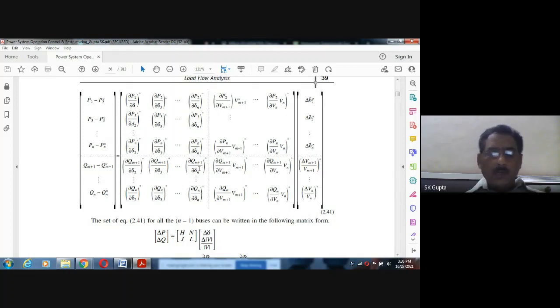And once you calculate this, take the inverse of this and multiply here, because with the help of MATLAB, it is not difficult to take the inverse of a 100 by 100 matrix. Then multiplying is also simple. Then this error or correction can be calculated. This correction will be added to the initial estimated value, then the first iterative value will be obtained. That first iterative value will be considered again, and the process will be repeated till two consecutive values are nearly the same, and we continuously go on. This is the Newton-Raphson method.